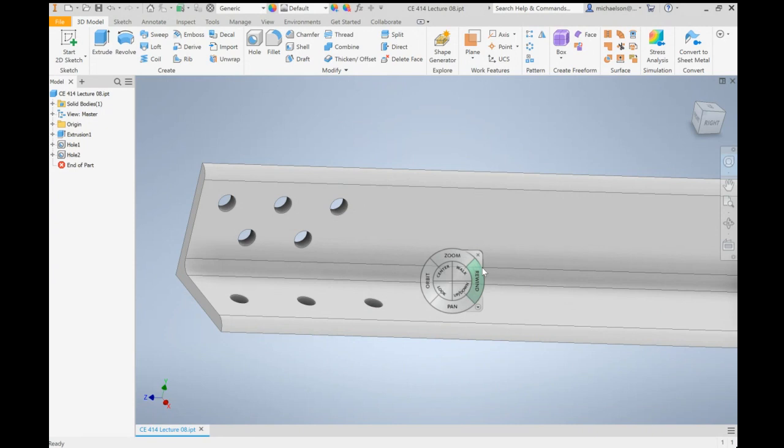Whereas this only has a total of about eight bolts in the entire member, and only three of them are on the lead line, so it makes sense that you could get it more quickly. I think it was homework 2.2 that connection had a lot of bolts, and not just a lot of bolts, but a lot of bolts on the lead line, so there were all sorts of different diagonal paths you could consider. Whereas this one, there just aren't that many.